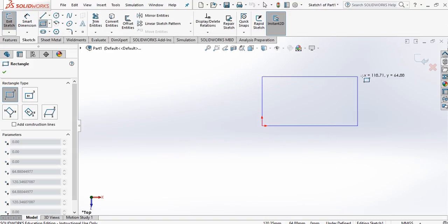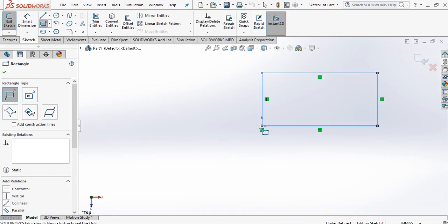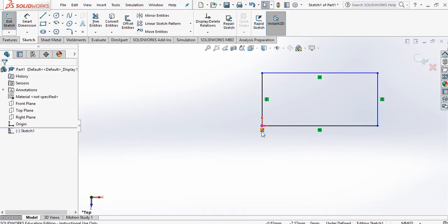So I'm going to draw this corner rectangle. I'm going to make sure that one of my corners is directly on this red origin point. And what that means is that one of these corners is always going to be linked to a definitive space. So what you see sometimes in a lot of technical drawings is that someone will draw this and it will be in the middle of space, and it's very easy for things to get moved, shifted, edited unintentionally. So by keeping something to this red origin point keeps things much easier to manage.